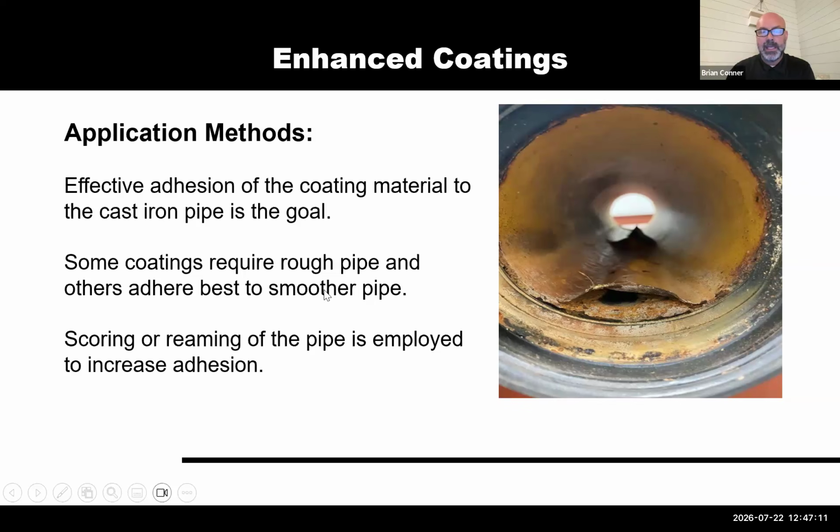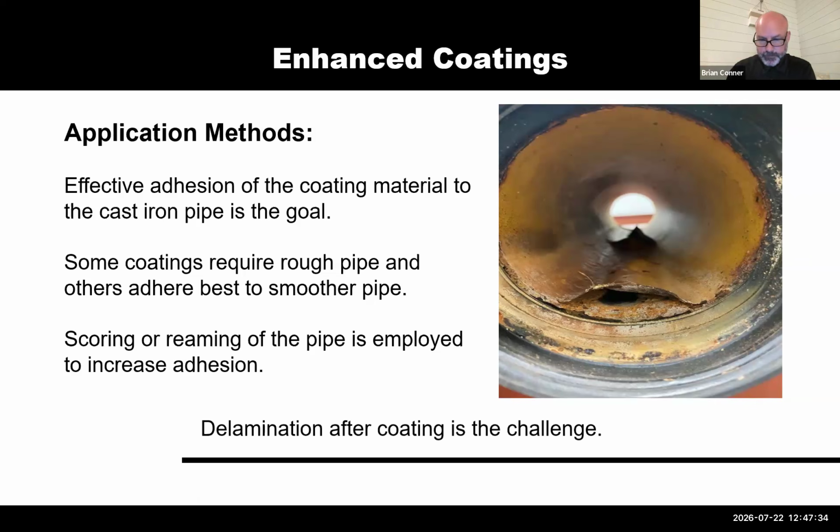Surface prep is key. It is, again, electrostatically adhered to the substrate, so there is no chance for delamination. Nothing can get in between the iron itself and the coating, and that is critical. And adhesion is the most important portion of the entire coating process.